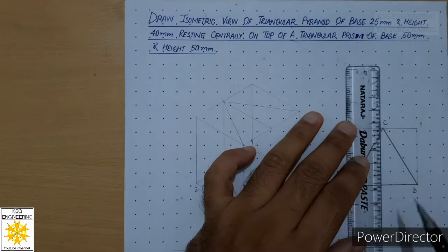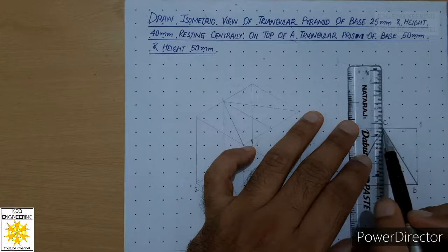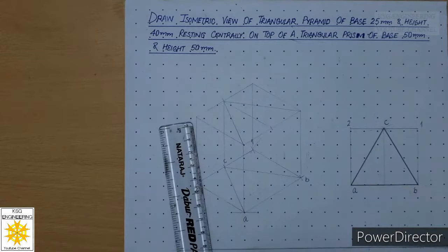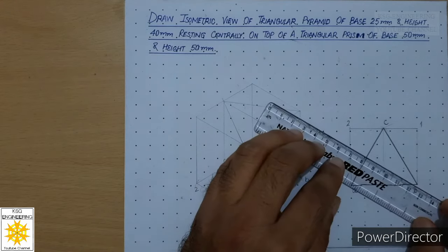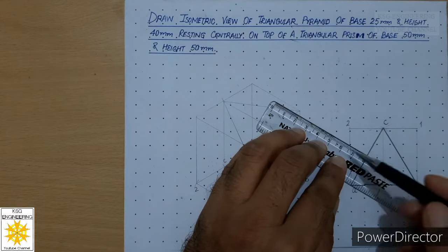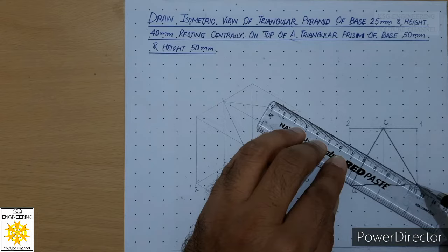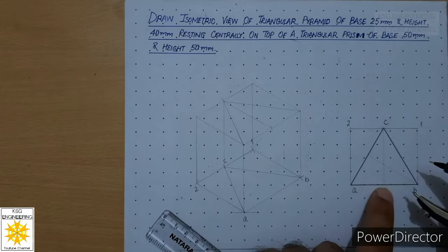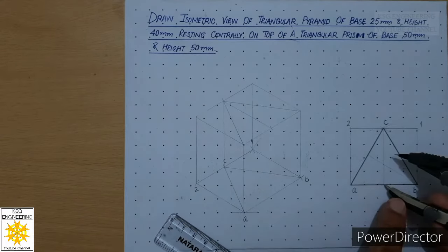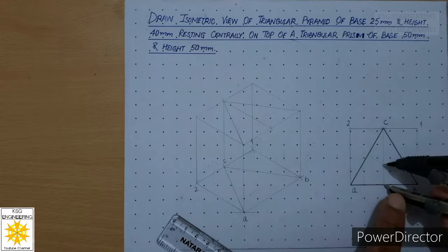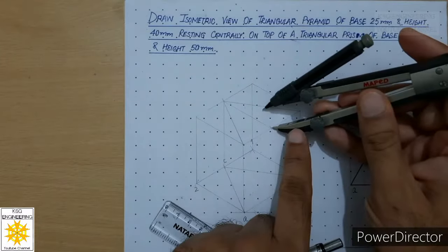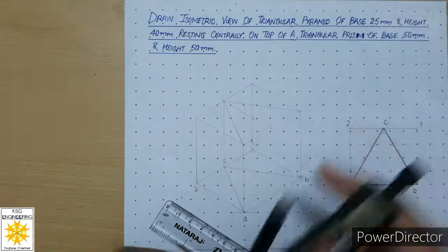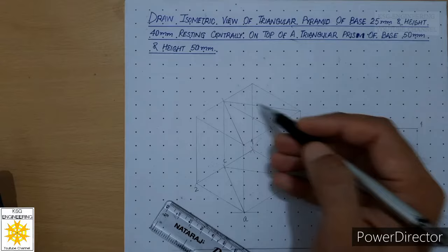We will draw a vertical line over here with a continuous thin line, and we will draw another line from this corner which will be perpendicular to the opposite side. So these are called as medians. So where these two will intersect, that is the center of the triangular face. So now we will measure this distance from the base. This point is over here. So we will measure this distance. And we will cut this distance on this center line. That will be the center of this triangular face.